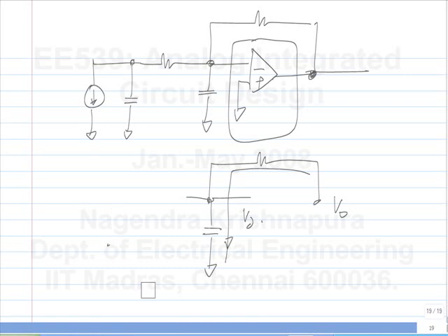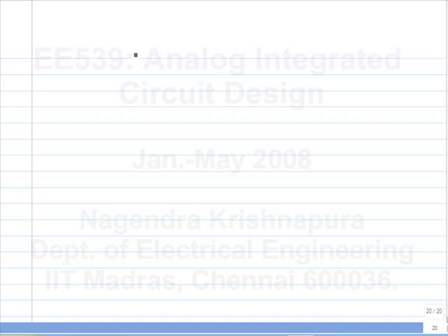Of course, the frequencies over which it happens may have been modified, but at high frequencies you get 90 degrees phase shift. So this means that the stability of this is also not very good. Only if you don't have this capacitance will the 0 help you. If you have this capacitance, you have an additional pole which will take the phase shift back to 90 degrees at high frequencies. Let's take this network.